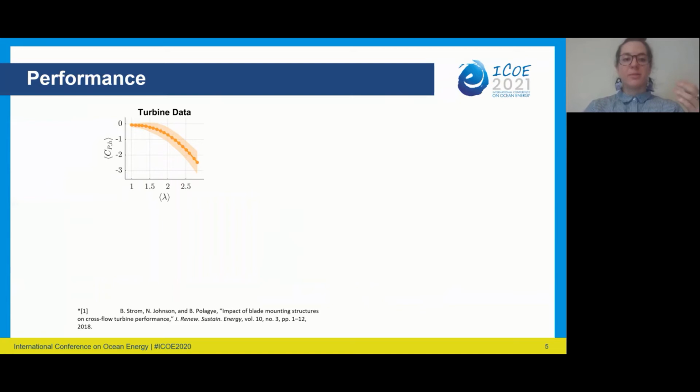However, for my turbine, I have those large acrylic plates, so there's a lot of parasitic drag from the support structure. And I'm specifically interested in tying the blade-specific flow features to the blade-specific performance. And so I want to be able to isolate the actual blade level forcing. And so to do that, I first take a performance sweep of the full turbine. Then I do the same thing for just the support structures, so just those big plates.